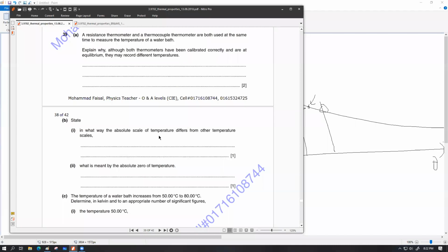Let me answer this question in a different manner. It is practically impossible to calibrate a thermometer for all of its possible temperatures, because if you think how many individual temperature readings are there between 0 degree and 1 degree, the answer is infinite. That's true, sir. But if we interpolate correctly enough. Exactly. And the smaller the gap that we take for our calibration process, the more precise, more accurate the reading is going to be, with much more decimal places being correct.